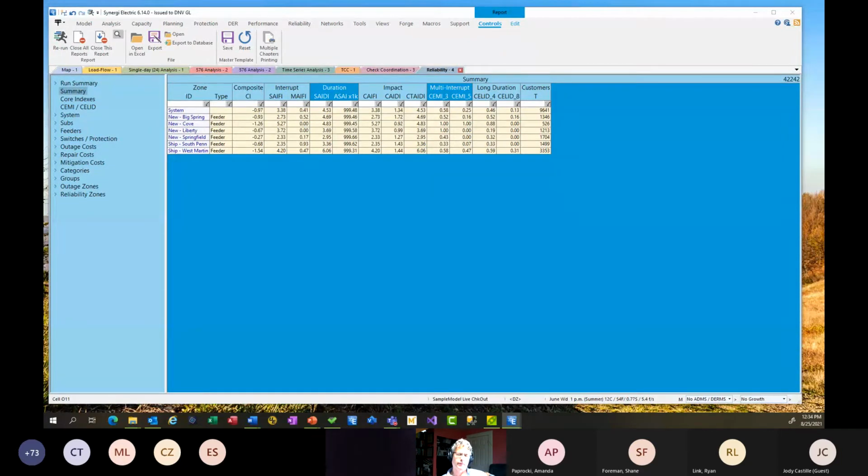So allocation is doing what load flow does. It's just backwards. It's dividing by the profile values to get the setting in the edit box, so that when you go and run load flow and it multiplies by the profile, you get the load that was expected during allocation. So anyway, your load profiles are not going to be changed.